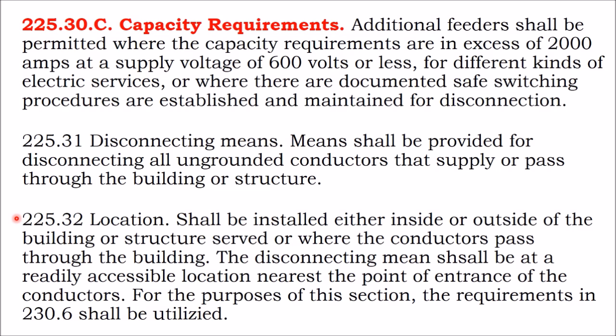So are you supposed to have it inside the building? Like, let's say you have your inverter and you have the option of mounting the inverter inside the garage or outside the garage. But inside the garage is a cooler space than outside, and so you want to put the inverter inside the garage. Less dust, less debris, a better air-conditioned environment, longer life out of the inverter, whatever. You're putting the inverter inside the garage.